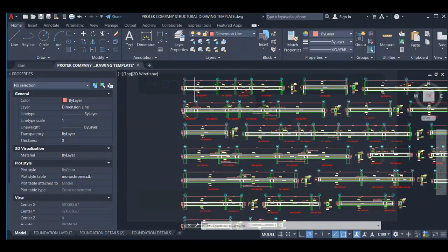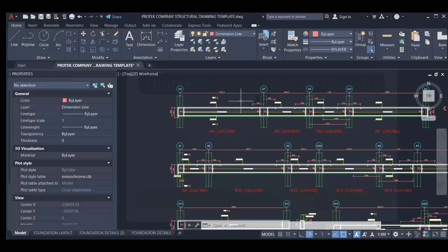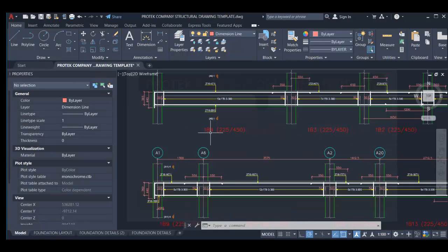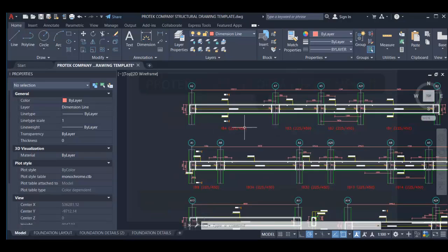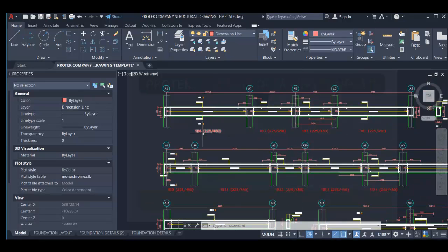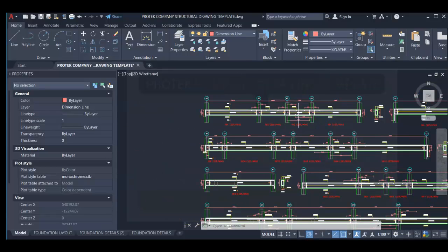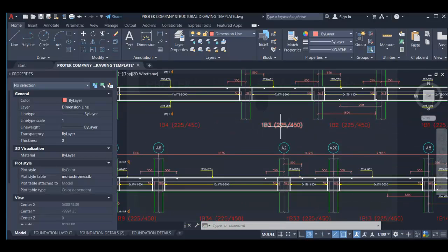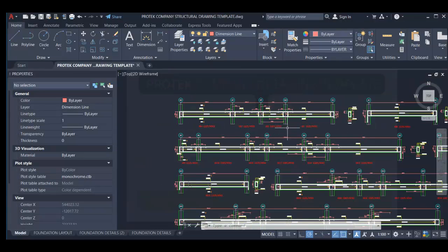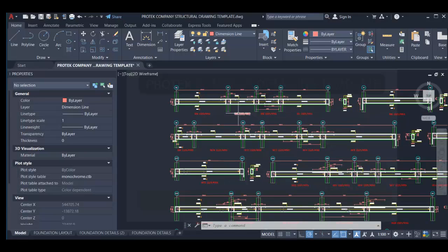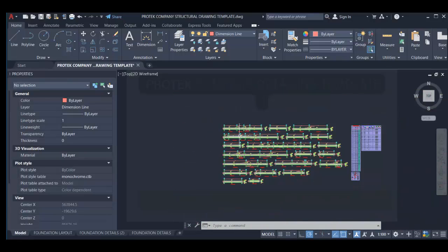All right, so if you check this beam very well, you notice that ProtaStructure details the beam as simply supported beams. All right, that is why you can see 1B4, 1B3. All right, but this beam from 1B4 to 1B1 is a continuous beam, so it's supposed to be labeled as a single beam, but Prota labeled it as a simply supported beam. So these are the changes we are going to be making to these beams in line with the plan view.